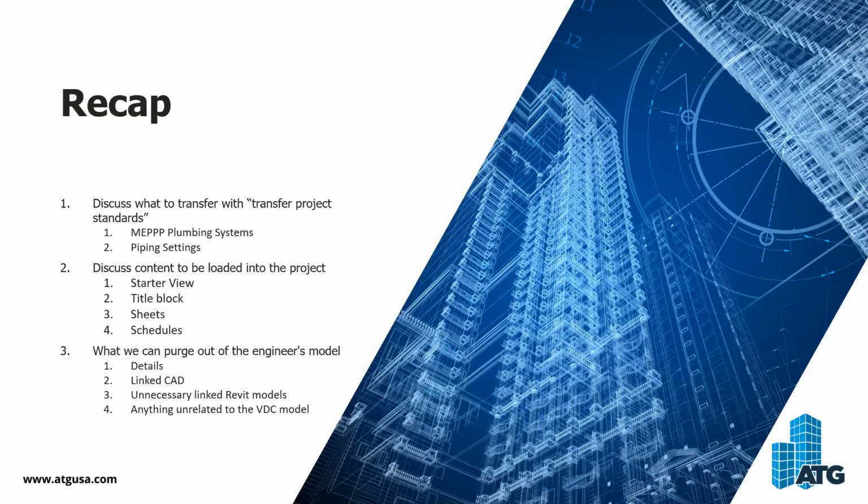what else we discussed here would be content to be loaded into the project. So we're going to want to bring our starter view across. We'll have our own starter view. We'll also want to think about bringing our title block that we're going to need. Any sheets we may already have created that we can just apply into the model, that'd be perfect. And then any and all schedules that we know we're going to need for the project.